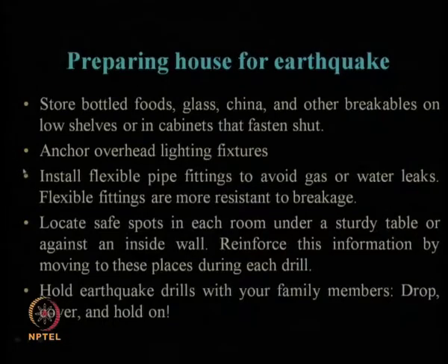top. Now, install flexible pipe fittings to avoid gas or water leaks. Flexible fittings are more resistant to breakage. That is, instead of rigid fittings on the pipe and water connections, you use flexible fittings, because they can take a certain amount of displacement during the earthquake, which will still hold those pipelines and water lines, but will not break. But if it is a rigid connection, there is a high chance that it will be broken during the vibration or shaking process.